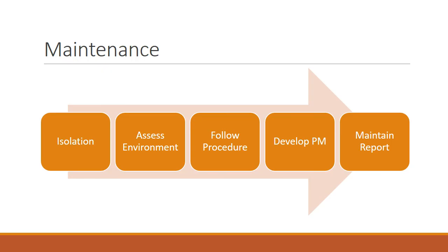Now to our third step, which is to follow procedures. Basic procedures for each type of switchgear that needs to be maintained, such as whether it's a metal clad or pad mounted switchgear, should be in place at the very least. Also, you should inspect if there are any surge arresters or PTs or CTs, as well as bolt tightness and insulating coatings should be considered specifically if they are present in that specific switchgear.